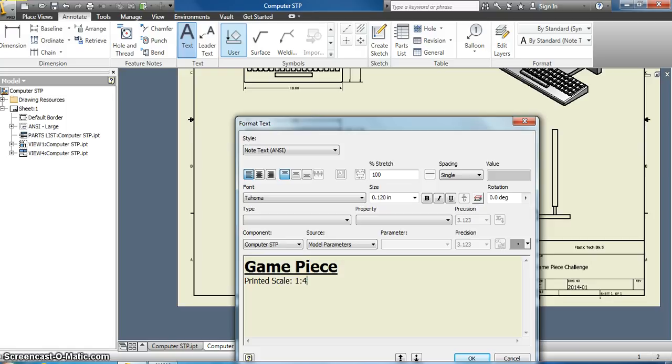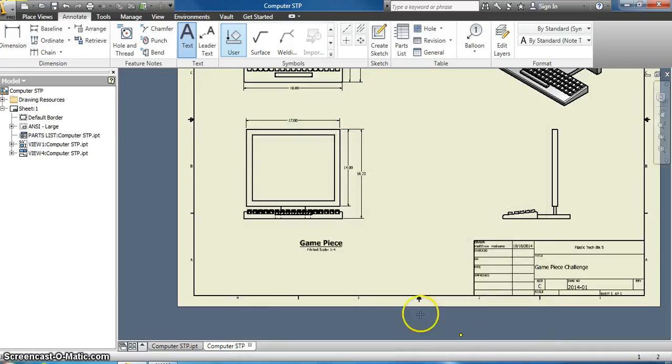at a fourth here. We draw it to full scale obviously, and what we're going to print out is going to be the quarter of the scale when we place those views in there. So we're going to indicate that. And I'm also going to select all this text here, center that, and click OK. Alright, and if I press escape, I should be able to move that where I'd like it.